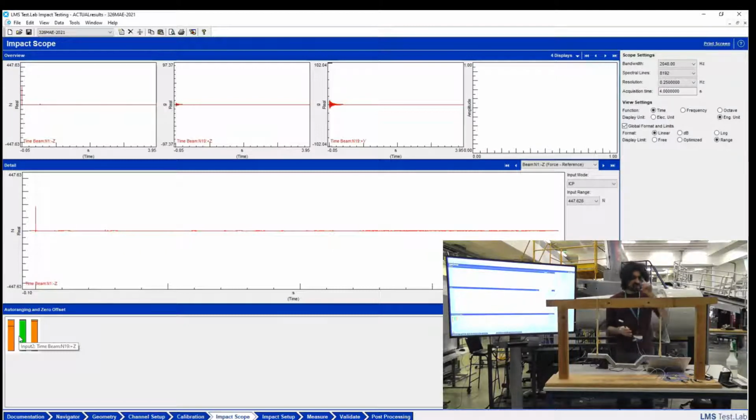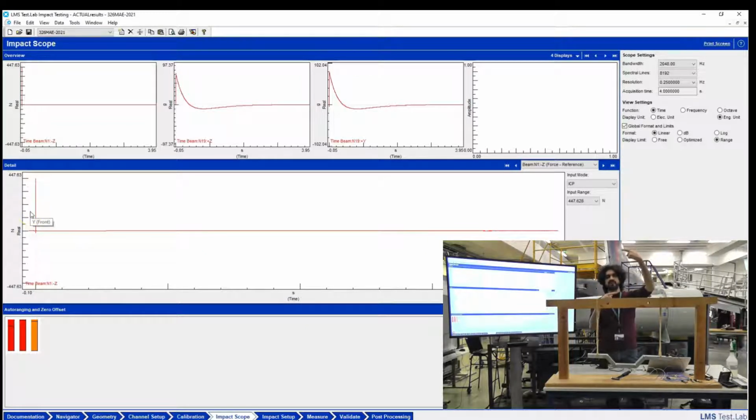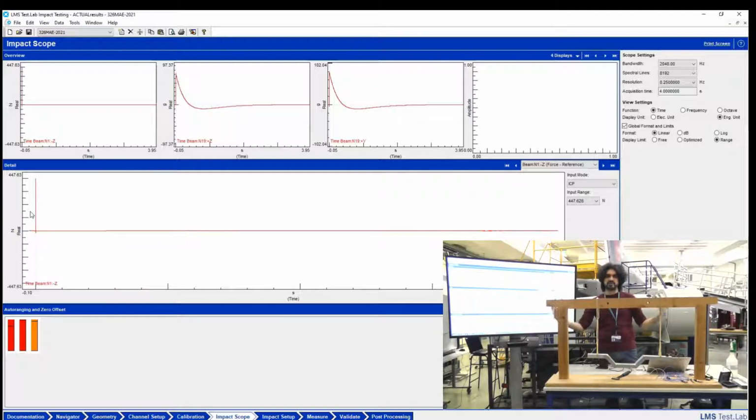Now this means that if your signal is too large, like this one, you'll get red bars. These red bars mean that your signal has clipped, so it's gone outside the possible range of capture. And this is bad because ideally the Fourier transform of a sine wave is a sharp line, but if you have a clipped sine wave, that's a shallow line that has leaked over the entire spectrum, and that's almost useless to you. So that's a very large error that you make over the entire range of frequencies.